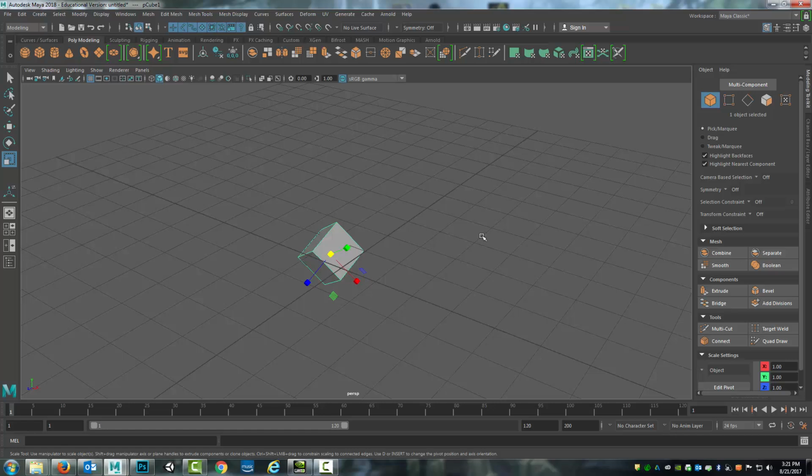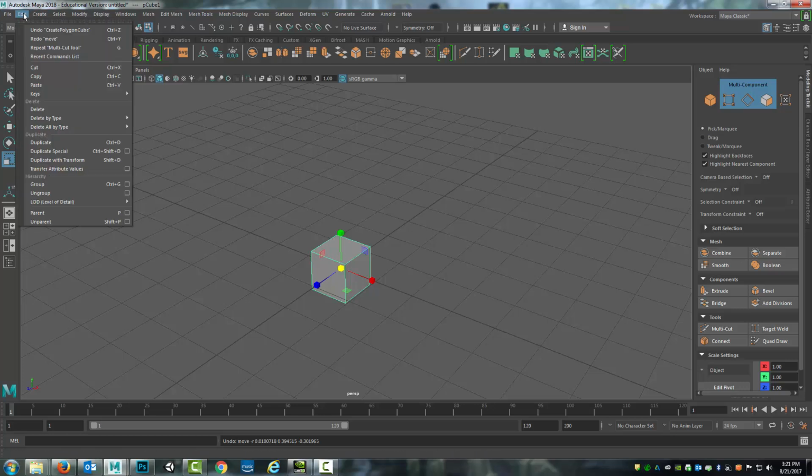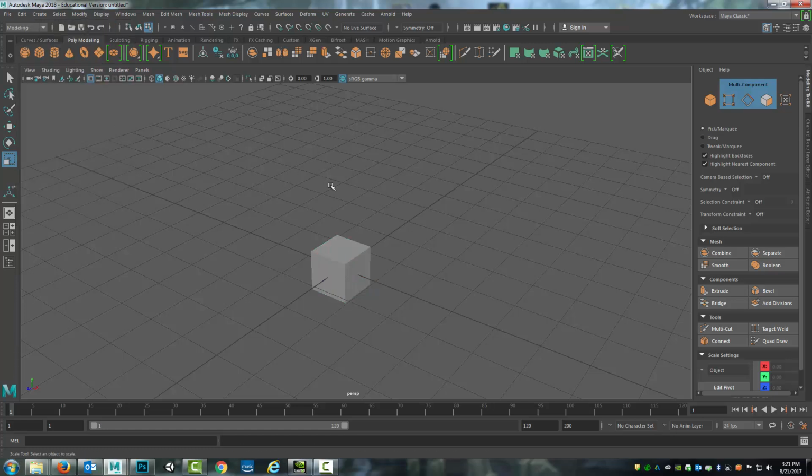The R key is scale, and because this is all disoriented right now, I'll step back. So once again, the undo hotkey is Control Z. So I can tap that quite a few times and bring this back to the origin. And if you're not sure where that is sometimes, if you go Edit, Undo, that's the same thing, and the hotkey is listed right next to it, so Control Z. So Control Z is going to be very useful. Please make sure you're familiar with it.